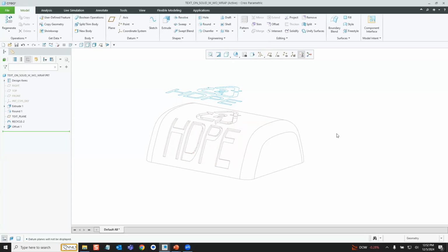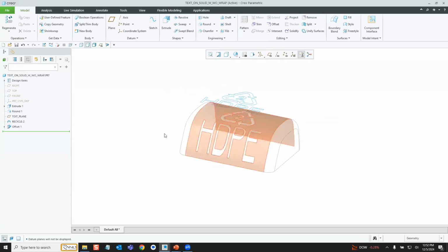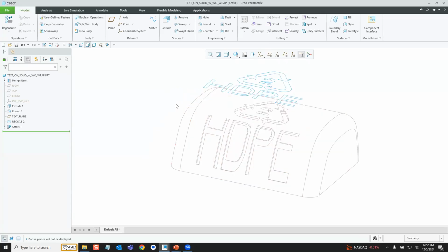Unlike the project, when you do a wrap, it's more like thinking of what you're wrapping as a bunch of pieces of string with a fixed length. The wrap is going to take all those pieces of string with a fixed length from the plane they're on and just drop them onto a surface. And since that piece of string has a fixed length, when I do the wrap, as opposed to the project that I have here, it's not going to change the dimensions.